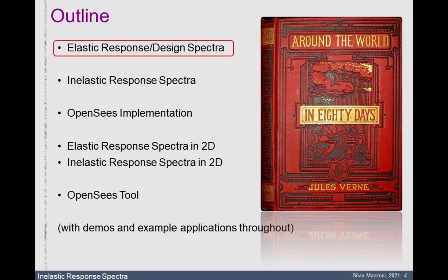We're going to start with elastic response versus design spectra, just the definition of those and how they're computed, because you need to know that to then go on to looking at inelastic response spectra. I'll give you some little demonstrations, and I feel like the little videos are helpful for picturing. I'm very much a visual person, so picturing what these different single degree of freedom systems are doing.